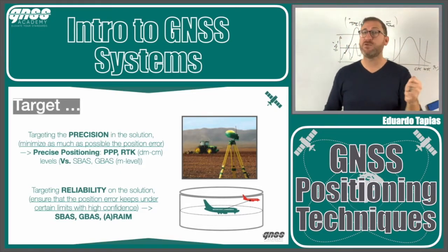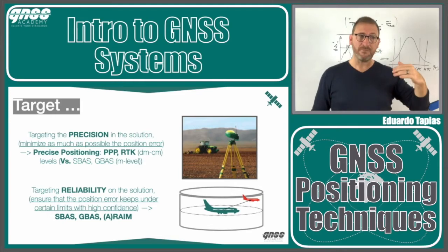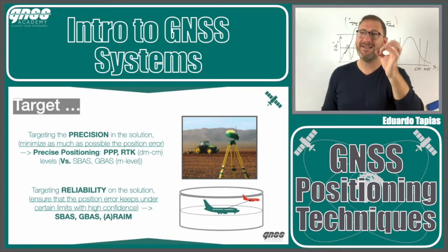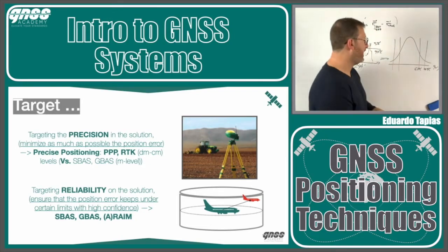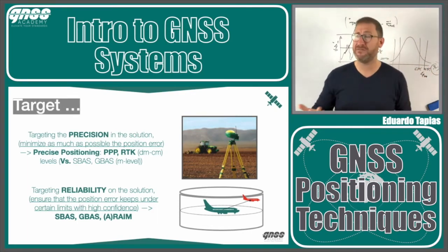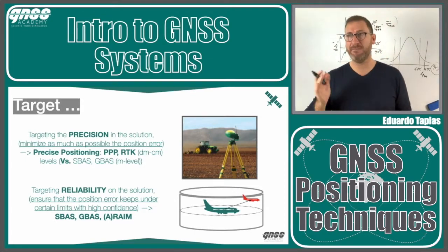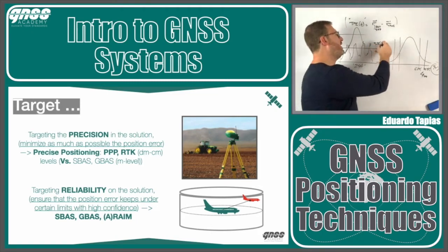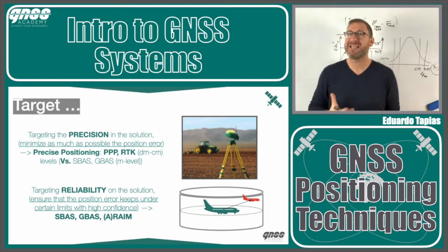Then the idea of this reliability, or of applications that are more safety critical like aviation, maritime, rail, is to give confidence in the solution. I want to have high confidence. What does confidence mean? If you give me 4 meters at 95%, this confidence is not enough for me. If you say you will be 4 meters precise at 95%, it means that 5% of the time I will be above this. It's not enough for me because I will crash. It's an airplane. 5% of the time is a lot of time.